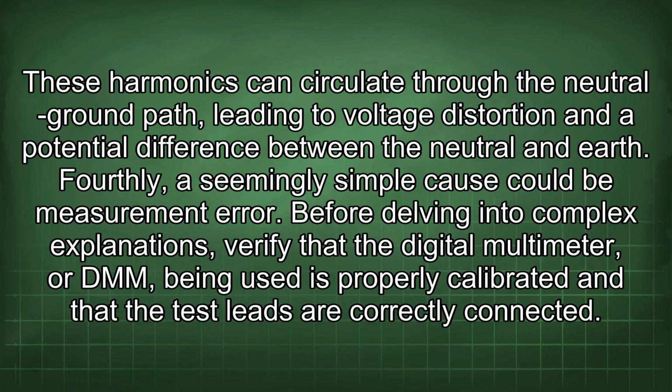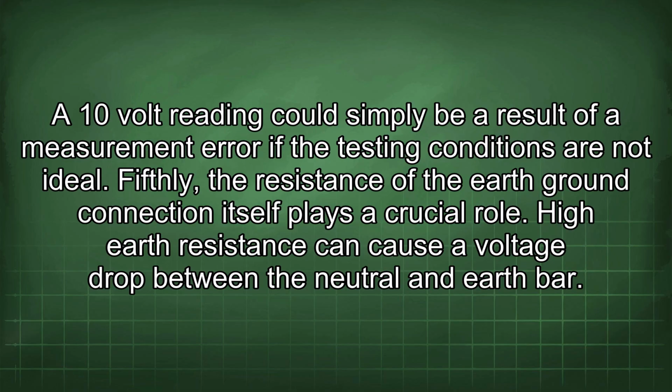Before delving into complex explanations, verify that the digital multimeter, or DMM, being used is properly calibrated and that the test leads are correctly connected. A 10-volt reading could simply be a result of a measurement error if the testing conditions are not ideal.